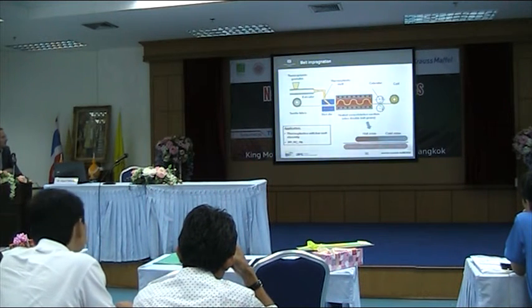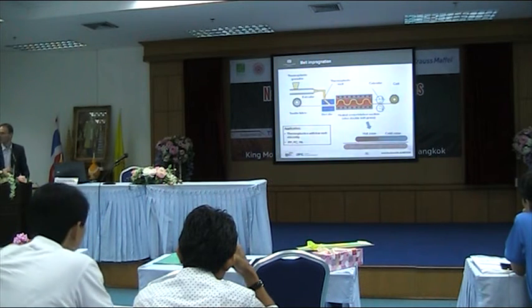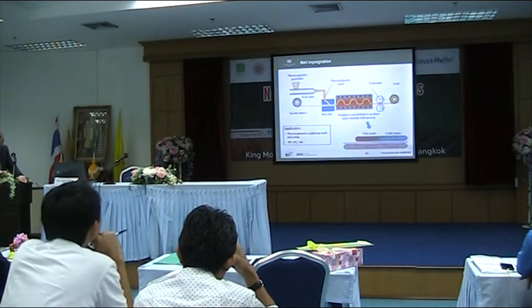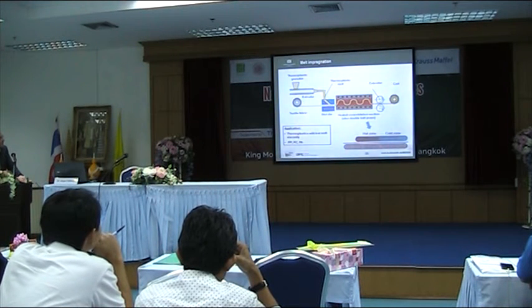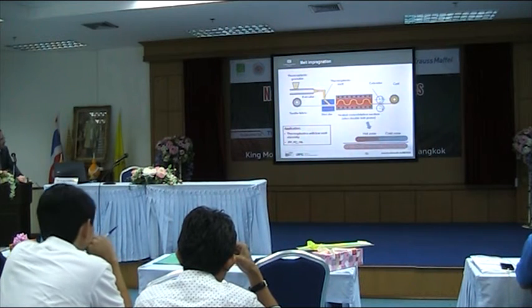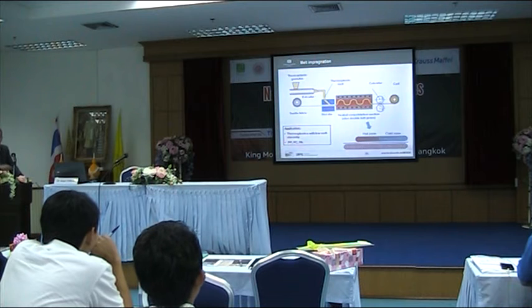So, one typical melt impregnation technique which is used is a thermoplastic melt, which you have from a slot die and goes directly onto the textile fabric. You have often a double belt press. You have a consolidation to get the thermoplastic melt inside of the prepreg, and then you have it roll to roll.